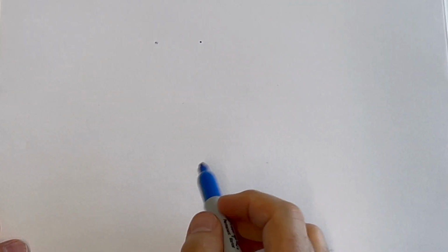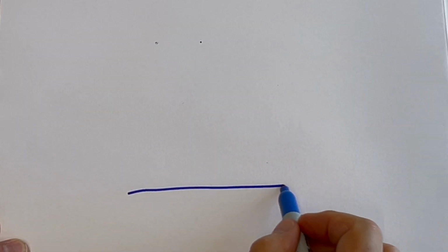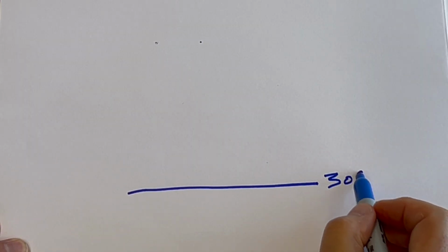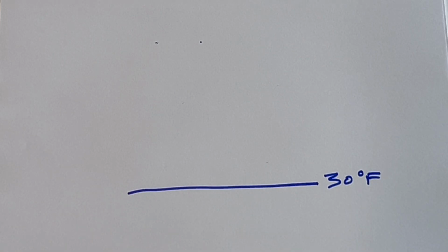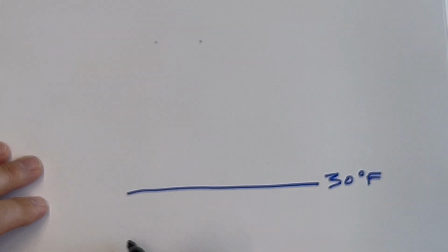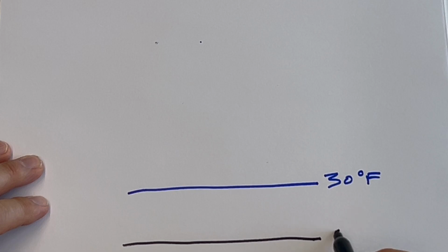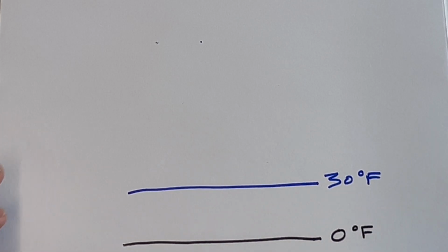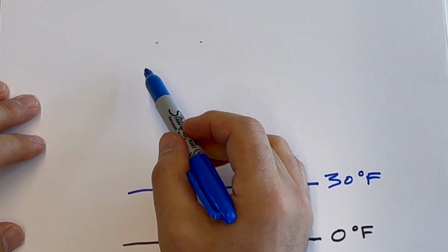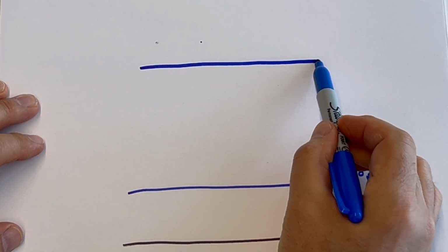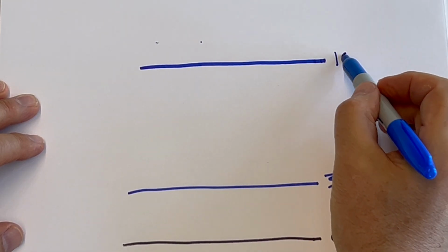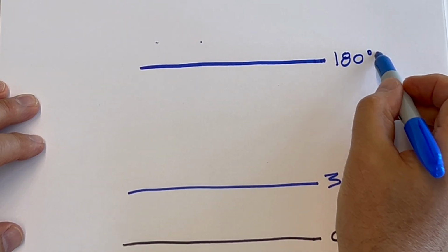Now let's use a heat pump to heat hot water. Instead of heating air directly, we'll first heat water and then that water will heat the air. Outside, we've got our typical 30-degree winter weather. What's the refrigerant temperature outdoors? We're using our rule of thumb. We're just going to subtract 30 degrees. That's the refrigerant temperature. But now instead of 70-degree air, we're going to heat it way up. Let's say we heat it up to 180 degrees hot water.